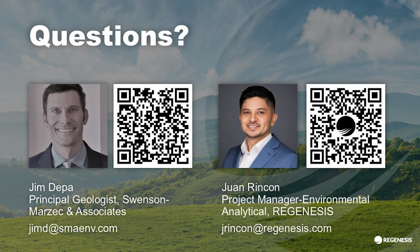I would be more comfortable doing it with MIP data or groundwater profiling tool data, where you're collecting analytical samples at various depths and use that to build an injection plan. But it can be done, and it is frequently done also from just monitoring well data.